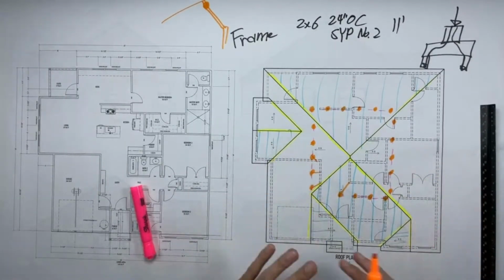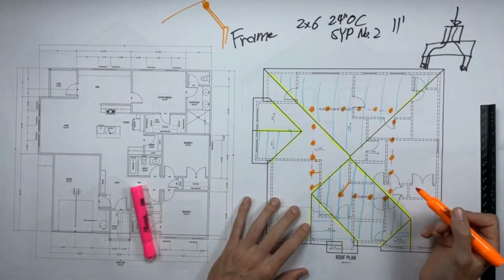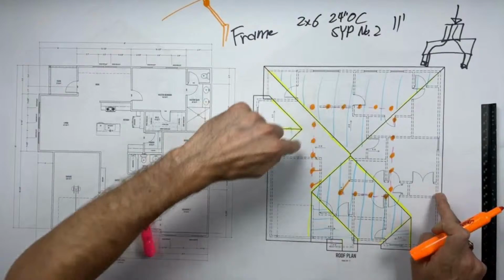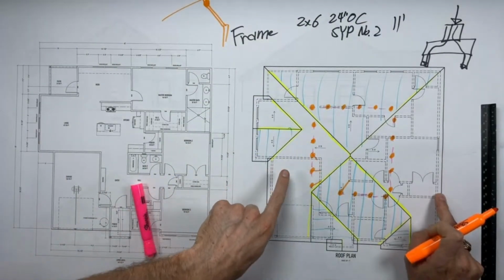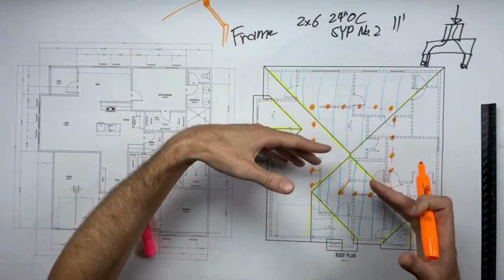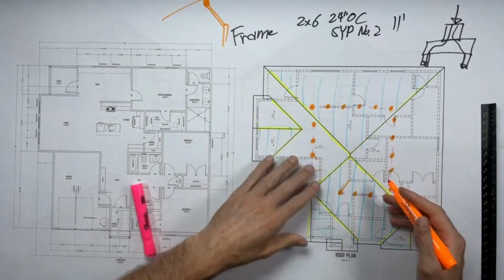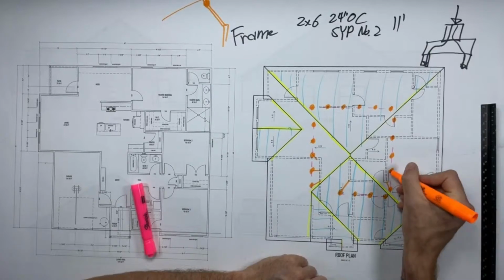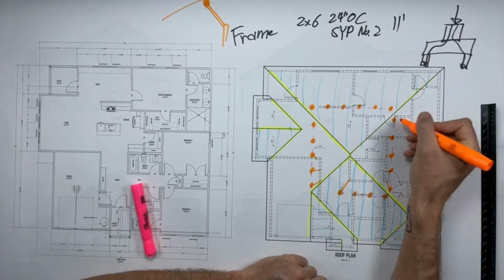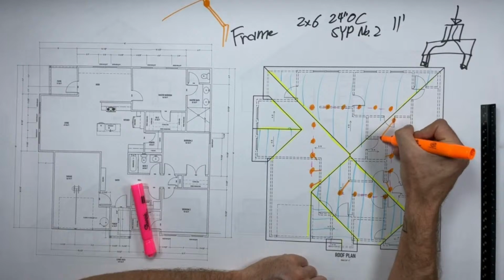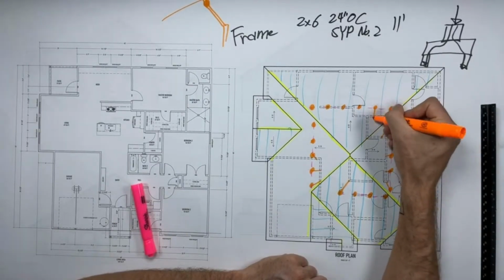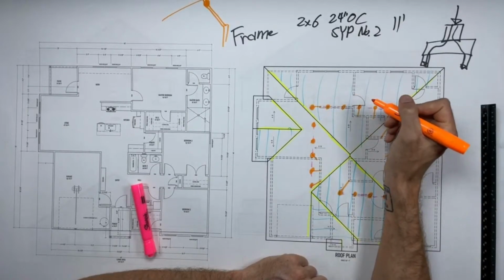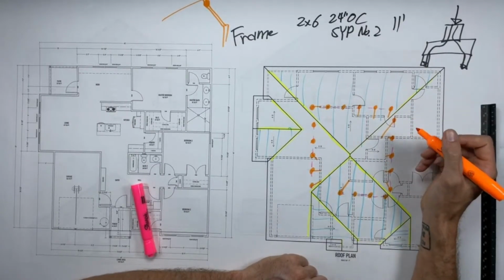Knowing the same thing, I could extrapolate that information and say, since these roof planes all start at 9 feet from a 9-foot wall, not this one, this one starts from a 10-foot wall, and we all go in about 11 feet, I have the same reach with all of these, which means I have a lot of reach. So this guy, I'd take and put over here. This guy, put on the wall right here. That one's already on a wall. This dude could probably reach over here to this wall. This dude could reach this wall, no sweat. And this dude's pretty high up, so it could probably reach over here and go to that guy. There's no problem with that.